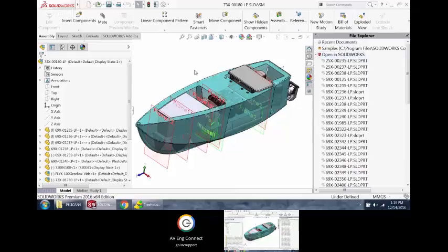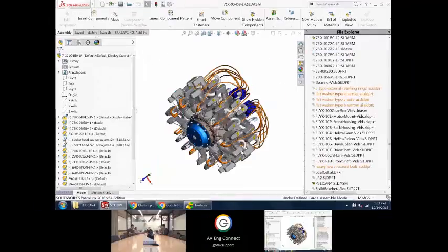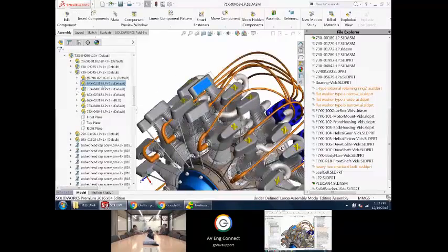There's some other layers to what large assembly mode does for you. So obviously, the first thing that you see is the fact that these items have a little blue feather in front of them. Again, like I said, what that means is that the parametrics, the metadata, all the supporting information from inside the SolidWorks file is not there. All it's showing you is the graphics and the reference geometry.